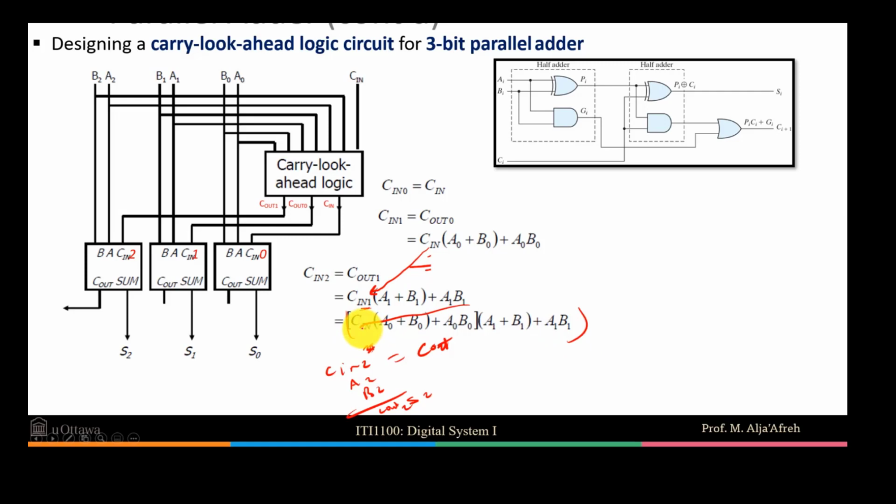Okay, guys? So basically, the carry look-ahead circuit will increase the speed of the arithmetic addition at the cost of increasing the complexity of your hardware or of your gates. Okay, guys? All right.